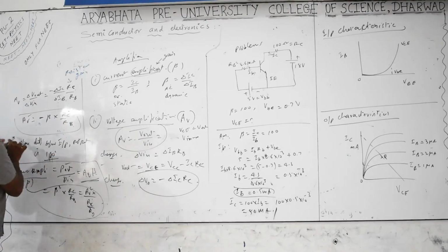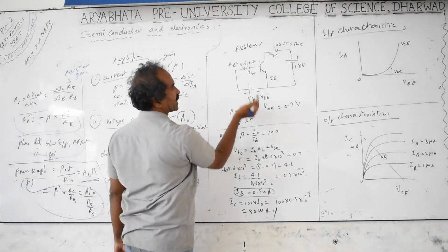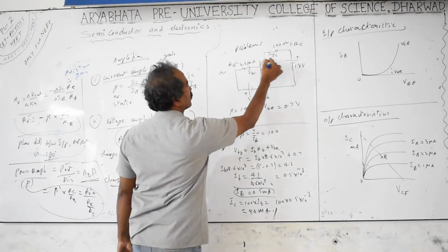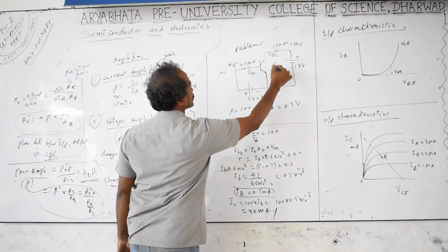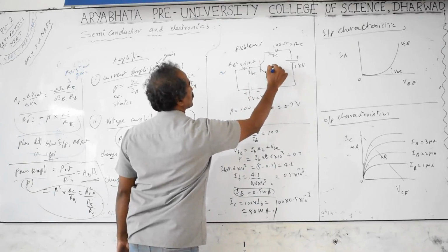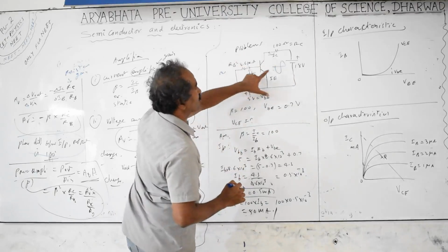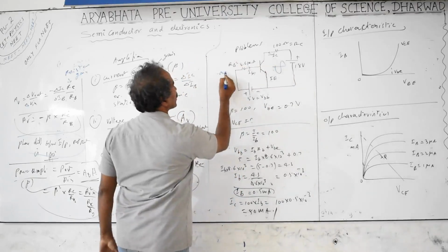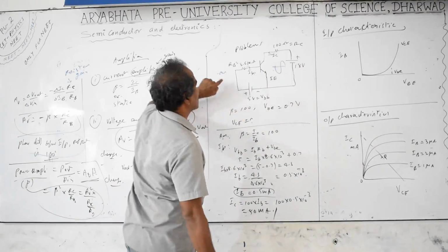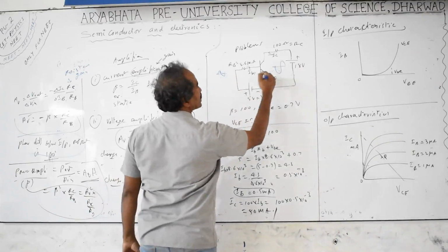And what is the phase difference between the input and output? For the transistor, when you give the input voltage, you get the IC term with a minus sign. If you give a small voltage at the input, the collector output voltage VC becomes very large, but it is out of phase. So the small input voltage gives a bigger output voltage because the VCC value is very large, but if the input is a positive signal, you will get a negative output, meaning out of phase.